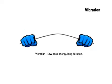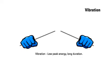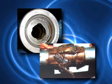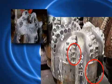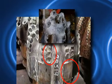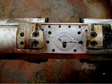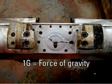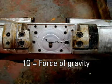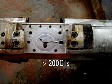Rapid and continuous vibrations result in fatiguing of the drill string connections to the point of twisting off. This is why many drill string failures are the result of cumulative fatigue due to vibration and have regular inspection periods. Shocks are measured in G's by an accelerometer. 1 G equals the force of gravity. Shock magnitudes registered via downhole tools can exceed 200 G's.